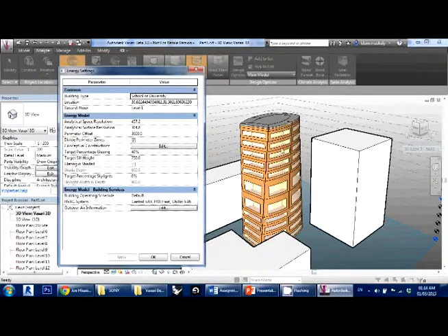as I've done here, you'll find that I started to have more zones, not only one zone for the whole level. I have multiple zones inside the core zone of my building, and this will help me more when I'm analyzing different types of zones. If I have a university building, it's not only about libraries or classrooms. I have different multitask zones, for example. Okay, so this is the parameter offset. If I change the offset, it will increase or decrease the area of my zone.